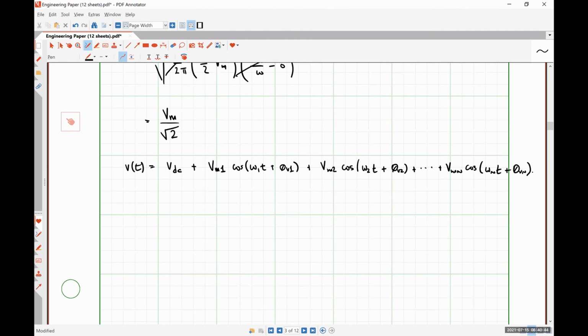frequency term where the frequency omega is 0. Based on our previous result, where the average value only wound up depending on the DC terms, effectively all of those cross-multiplied terms get thrown out when we're looking for an average value, and we're using this stuff to figure out these effective values to calculate the average power. We would find that the effective voltage in such a situation would simply be the effective value of each of the frequency terms squared, summed together, and then we take the square root of the whole thing.